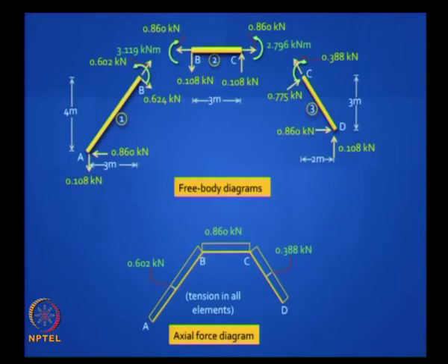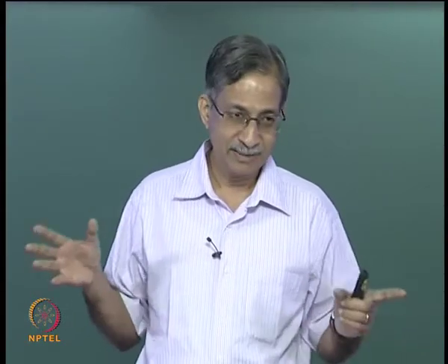And these are your final diagrams. You have got your axial force diagram, shear force diagram, and bending moment diagram. The axial force diagram is more critical among these, and you will find that they are very small. So this simple problem teaches us many things and shows us the power of matrix analysis.